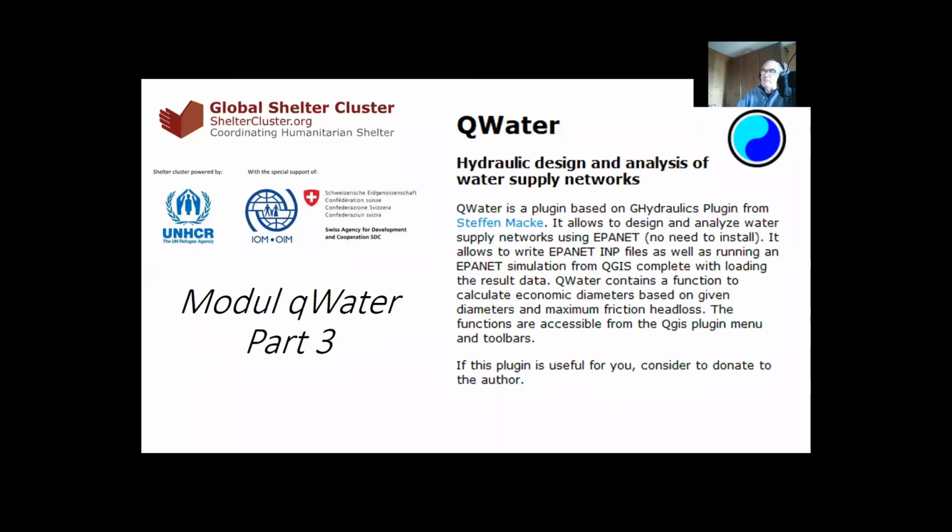But finally, I understood that this plugin of QuantumGIS is not finished yet, and it can make only situation analysis or simple analysis. It cannot make time analysis, and additionally, it cannot include a pump because you cannot put the pattern. But what it does, which is good, it gives the length of the pipe automatically, and additionally, it gives the elevation of the junction automatically based on the digital elevation model. So let's start with this presentation.